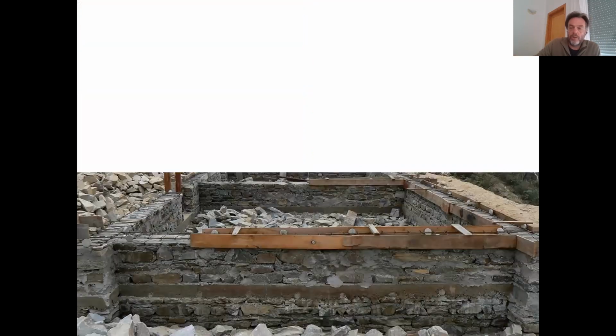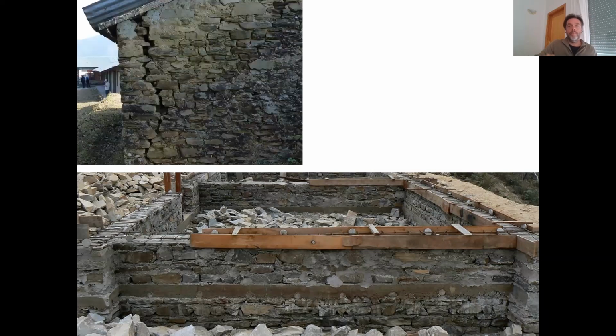And then I also started looking at the typology of masonry. Now, what we see here is what I built. So I built very neatly coursed masonry. We tried to make some rows of the stones in here with cement mortar, but also with horizontal bands. I didn't do the vertical steel. This, of course, is something completely different from completely unreinforced masonry.